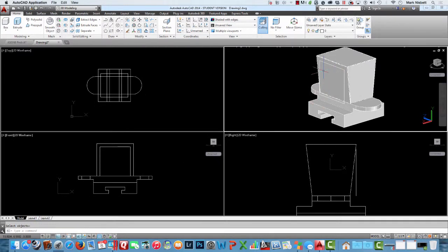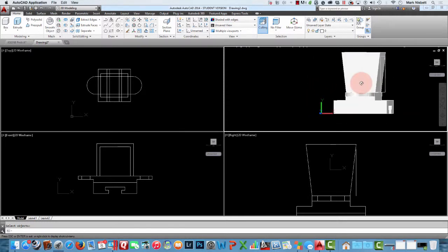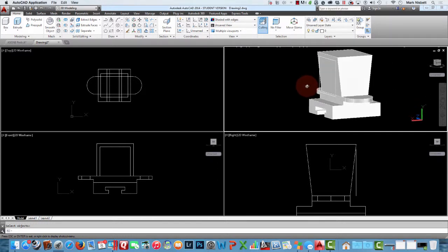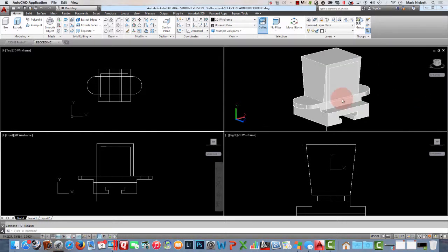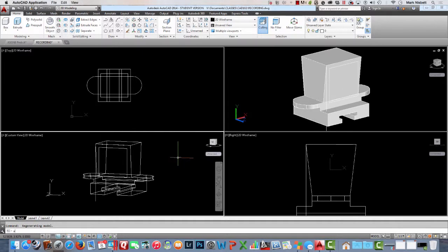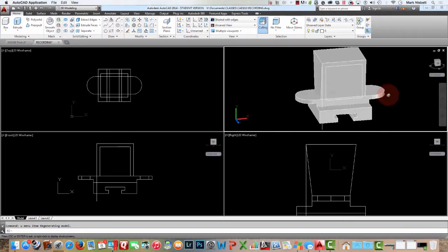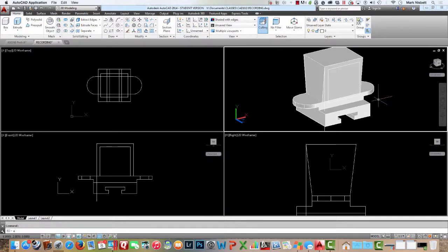So now over here you can see we have this box. Okay, you can see the box and it's not in the same plane. You can see how it's not going like that, but all we have to do is punch it through and subtract it. So now that we have our rectangle created in here, whoops, wrong viewport, we can see that it's there. I got another construction line there I got to get rid of.